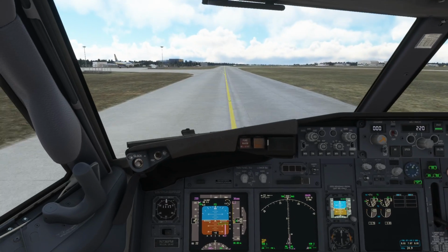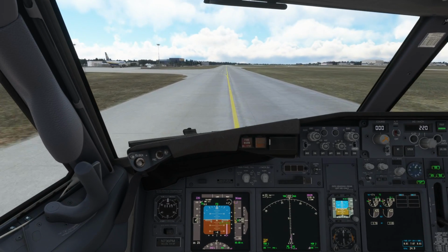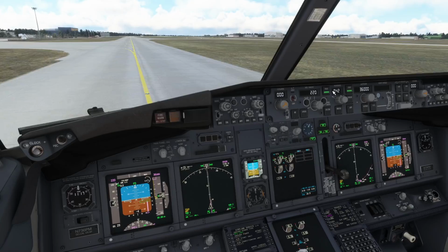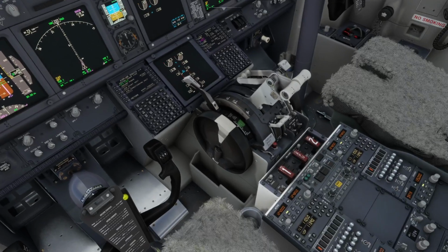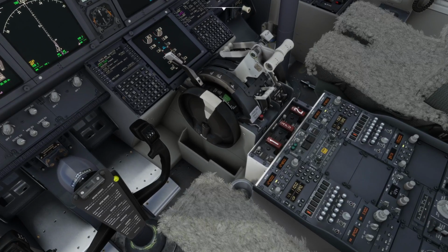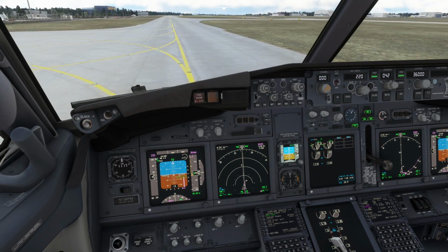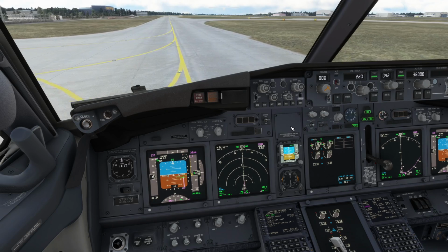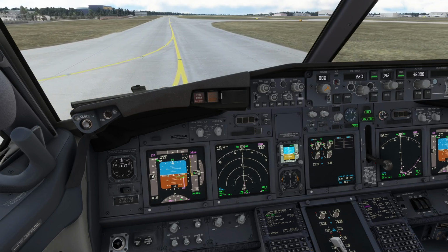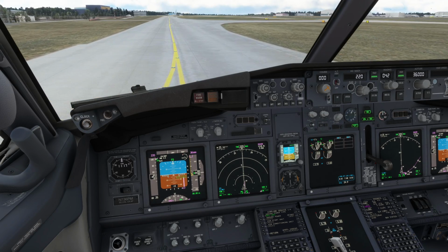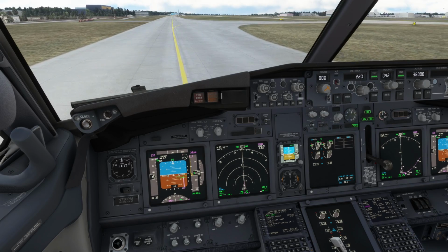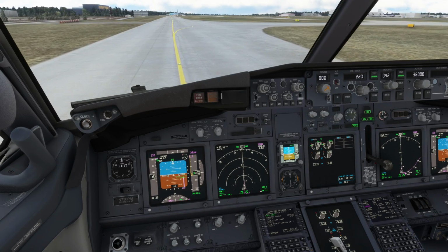Okay, is there anything we need to be doing on our way down the runway? We've got the target airspeed ready. I guess we could get TCAS ready, so we'll go and put it onto TARA. Strictly speaking, for takeoff you shouldn't have it in TARA, it should only be TA, so the autopilot won't try to avoid other aeroplanes. And then you go to TARA once you're at altitude.